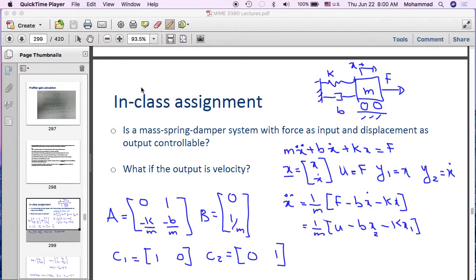And we've been working on methodologies in solving the problems by hand, as well as using MATLAB to find the proper control gains to place the eigenvalues where we want them to be. And of course, we choose the eigenvalues to create a certain behavior in the system. Furthermore, we talked about the next component in a state feedback controller, which we call a pre-filter, another gain that guarantees that the steady state error goes to zero. So Y matches R in steady state.